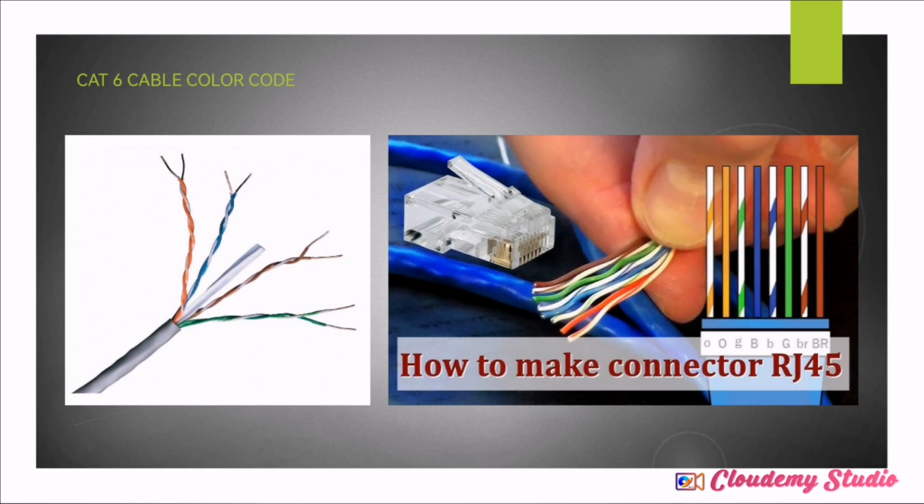You want to use it for the internet connection from the router, then you find that the computer is not connecting to the internet, meaning you have made a cable that doesn't match the color code. So it is important to master the color code.